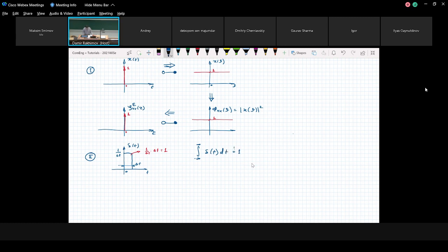And now what I'm going to do is calculate the energy of this approximated delta pulse. Because for the next step, when we calculate autocorrelation for delay equal to 0, we calculate energy. 1 over delta t times delta t, squared, equals 1 over delta t. And this is the amplitude of the autocorrelation function for tau equals 0. I show this autocorrelation function below.